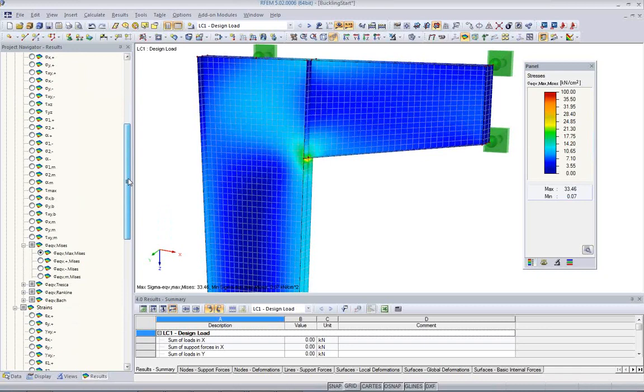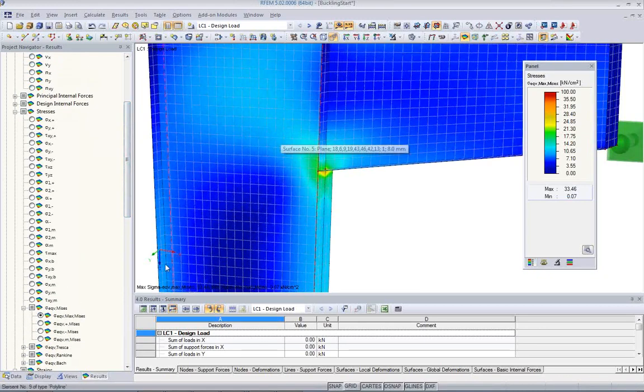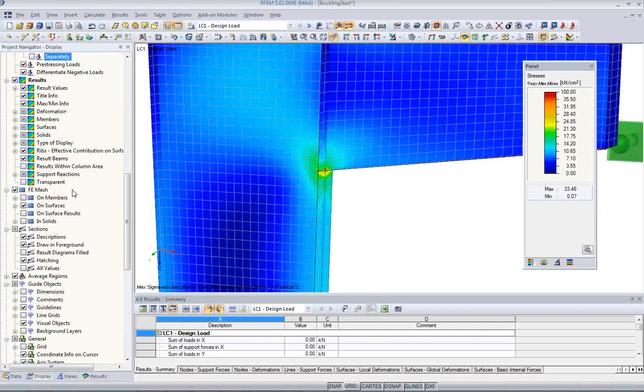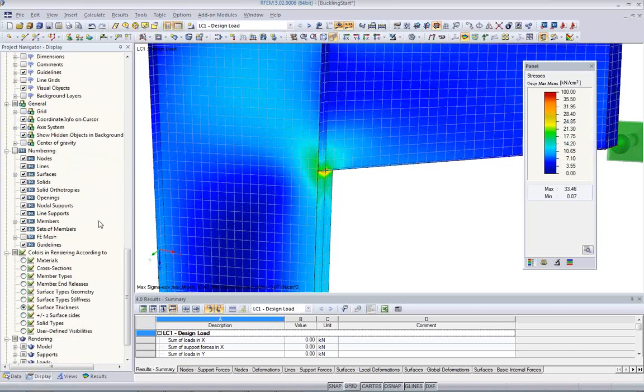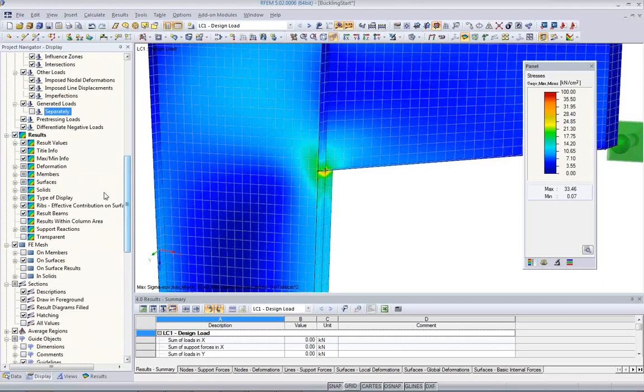First of all, for each mesh cell we change the stiffness. And therefore it is not a good idea to smooth the results, which is what we do by default over all surfaces. RFEM has a specialty in how to display results. In general, you get rough results and you want to smooth them over one surface. But when we look at the plastic design and we change the stiffness per finite element mesh cell with one elasticity modulus, then we have a constant stiffness over the mesh cell, and we cannot change the stiffness in each point. So we have to look at the results constant per mesh.